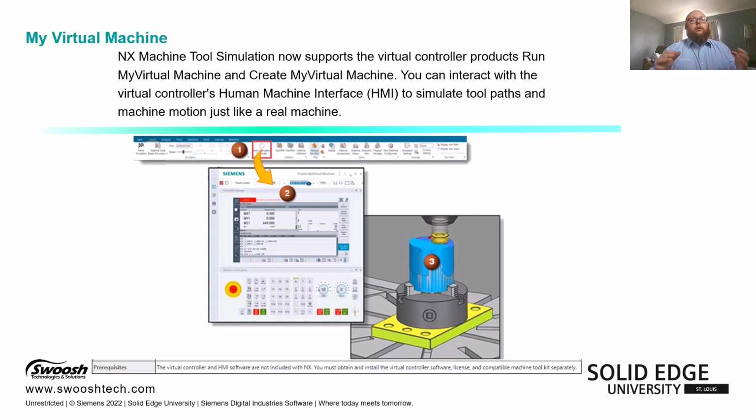So when you have your machine kit configured through this VNCK option, this virtual numeric control, you're actually taking the archive file out of your machine tool, so you're getting all of your parameters, tool data, offsets, things like that, and running the simulation using all of that data, not just what's inside of CAM Pro itself.